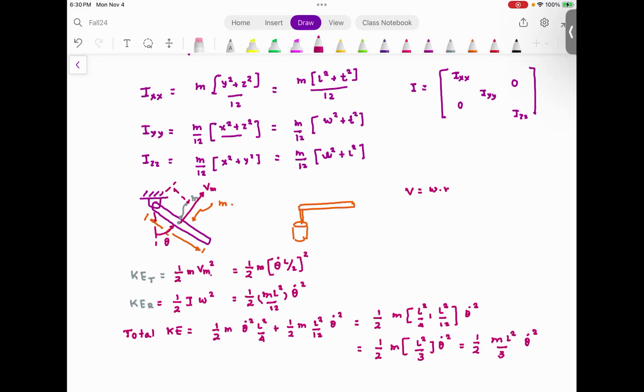If the mass is distributed and the robot is pinned anywhere other than the center of gravity, you basically add the mass at the center of gravity. So for example, you have this slender rod where the entire mass is distributed across its length. The whole mass is located at the centroid shown as the black dot. That is where the mass is located.